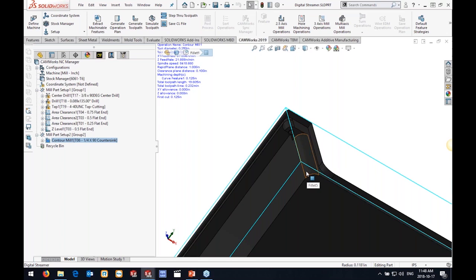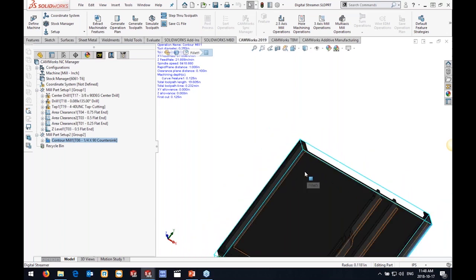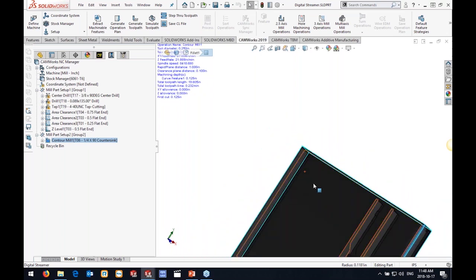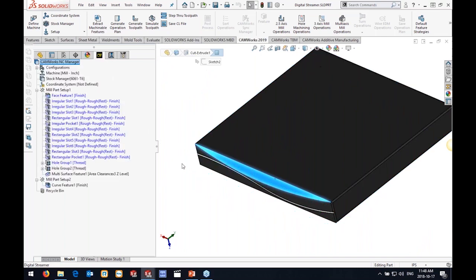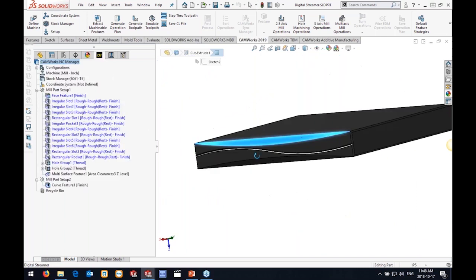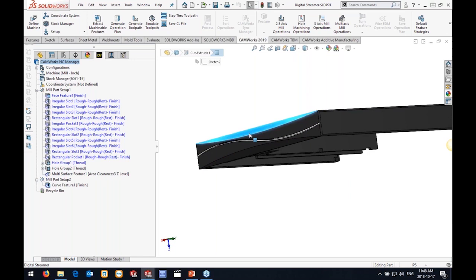And by doing this and working through different iterations of your design, you end up changing your model, and you may end up with things that might need to be 5-axis machined. Now, 5-axis machining can be notoriously difficult. In this case, what we're going to do is put in a couple of swarf machining toolpaths here to go and cut these two chamfers on.